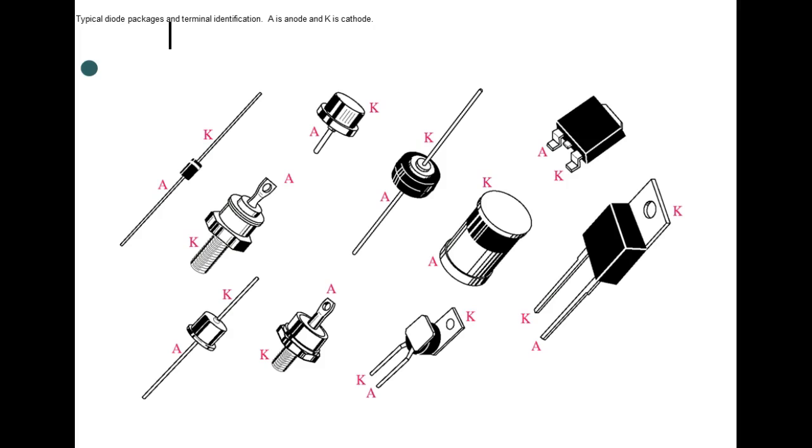With an ohmmeter, right? Everybody understand that? Real easy to identify. Very, very easy. And it has drastic consequences, especially in a power supply. Usually in a power supply, if you put the diode in backwards, you're going to create a short circuit. So you better honor the diode. A lot of times they'll paint it or silk screen the symbol beside it.